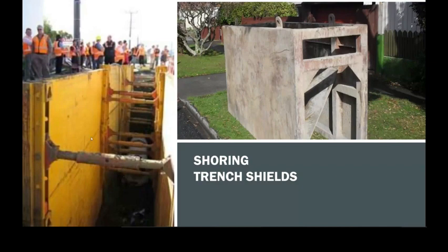The advantage of shoring is it actually supports the trench face as well. So it's more suited if you're on a roadway and the car still had to drive past, it would actually support that trench face. A lot of these ones can actually be dug in by a digger, and it digs inside it and then it pushes it down as it goes. And it can also pull it out again. So you don't actually have to be in there building it or anything. You get in there after it's installed.